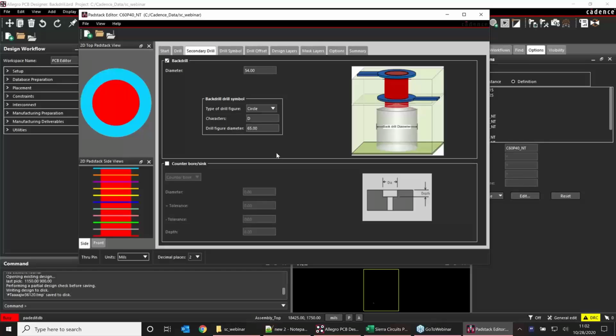So let us say you have a 12-layer board in which there are 12 conducting layers, and your overall thickness you want to be around 62 mils. If you subtract from that all the copper thicknesses, you can roughly divide by the 11 dielectric layers in between, and you will get an approximate idea of the average dielectric thickness you want.